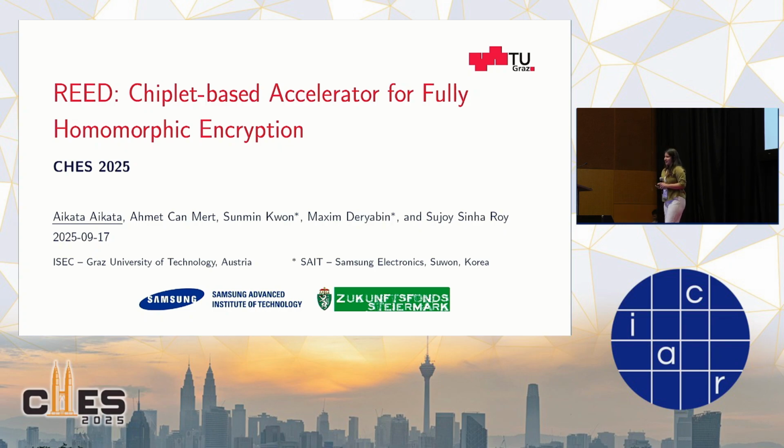Yeah, sure. You need a transpose in 4-step NTT because you want to use unrolled NTT when you first process the columns, and then you do a transpose so that you again have the rows in column format and can apply the unrolled NTT again. But instead of processing columns, we process rows via pipeline NTTs. So we're not using an unrolled NTT combination, we are using pipeline NTTs along with unrolled NTTs. And these pipeline NTTs result in data which we can directly feed to unrolled NTTs.